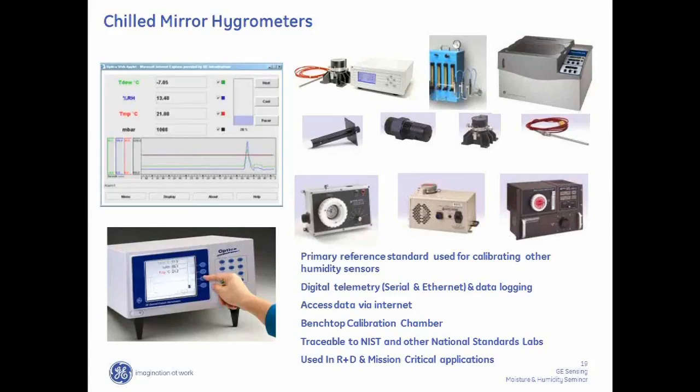The heated chilled mirror, as I mentioned, heats all of the wetted surfaces except the mirror. And the idea is when you're looking at elevated temperatures, the mirror cools down just to the dew point, and it prevents condensation from occurring in the system.